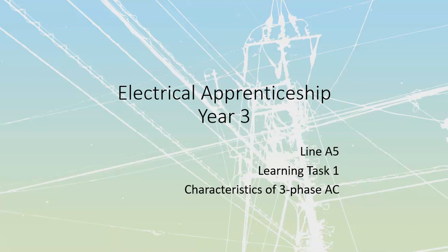The reasons for three-phase are listed, some of the better ones down below over here. The first one: it's possible to create smaller machines with the same kVA capacity, so we can get the same power out, we just get a much smaller package, which also means it's going to be much cheaper because there's going to be less material required. The next reason, we have better distribution systems. We can distribute more power using less copper. Once again, all of our copper and aluminum costs are high. We want to stay away from that.